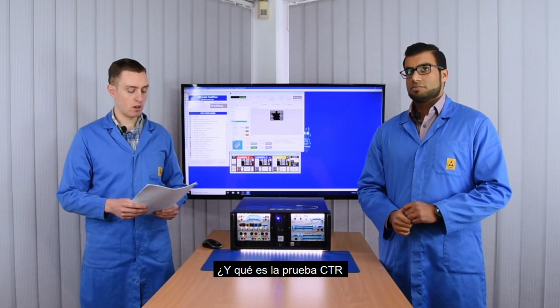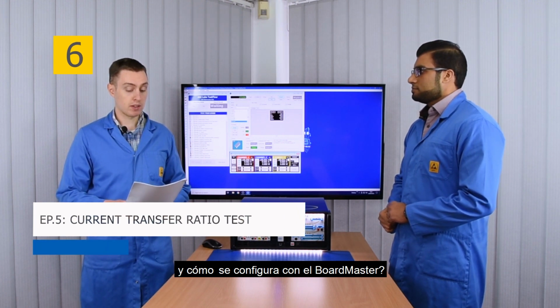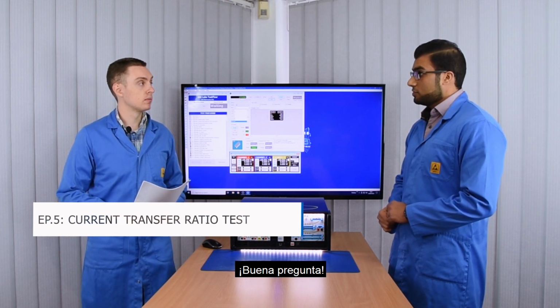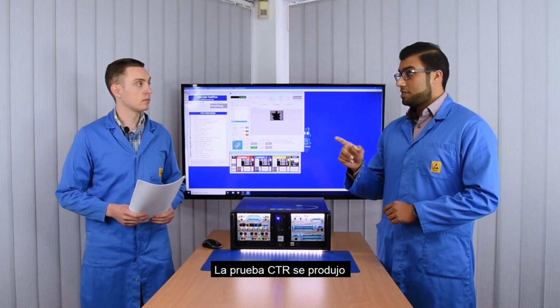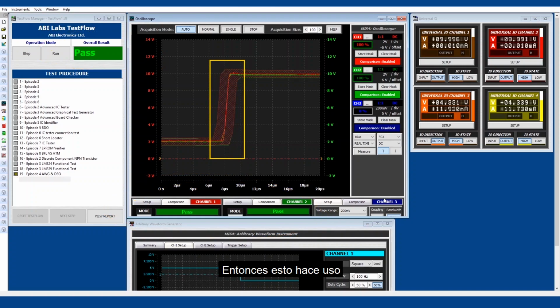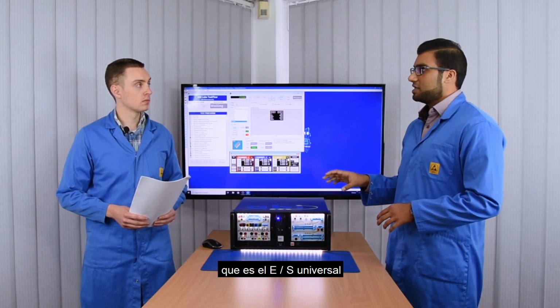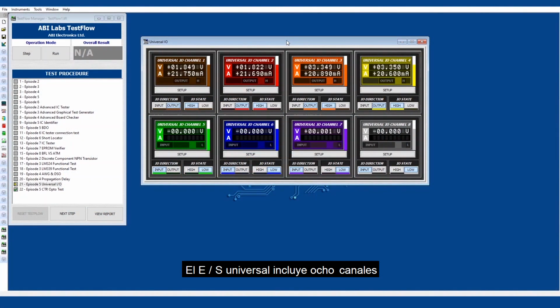Okay, fantastic. And what is the CTR test and how can it be set up by the BoardMaster? Good question. So the CTR test came after the test where we showed the propagation delay. So this makes use of another instrument available with the MIS4, which was the universal I/O. Now the universal I/O comes with 8 channels.